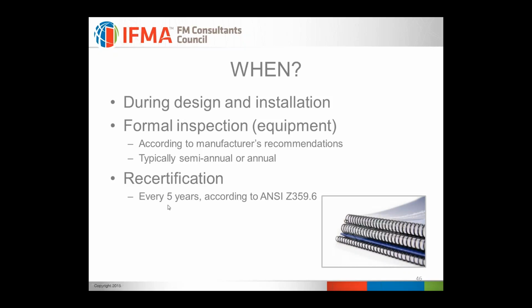That's what the point of recertification is really all about: verifying that the codes and regulations haven't changed, or the conditions where the system is being used haven't changed. So for example, if there was a process put in place underneath where this particular fall protection system was to be used, if now you don't have the same fall clearance that you originally had, maybe that's a reason to modify the system.